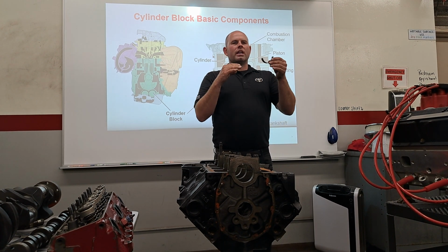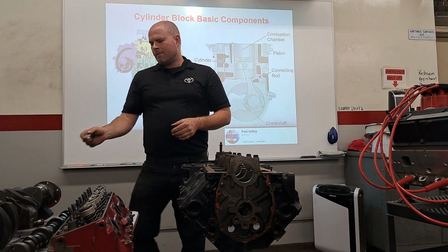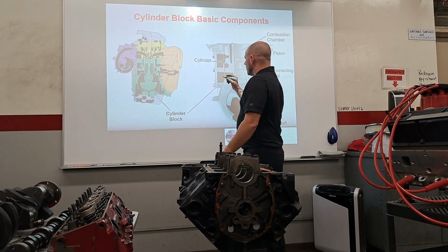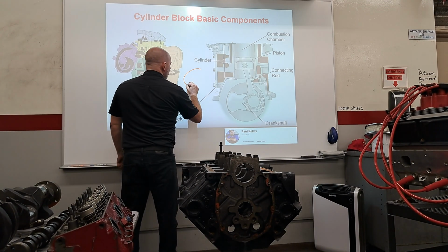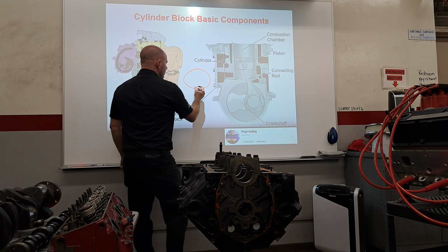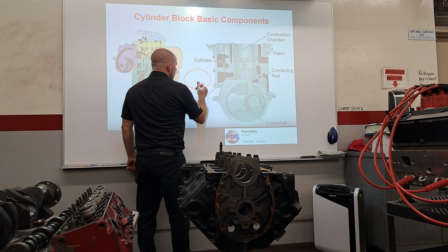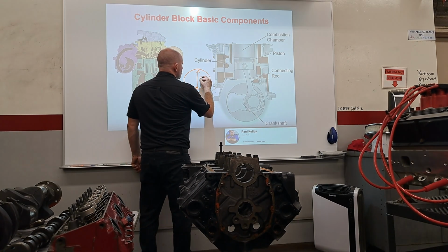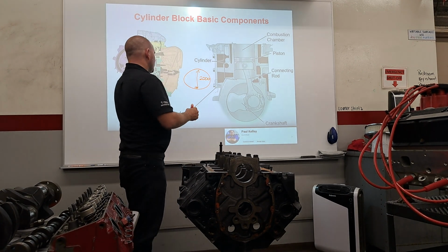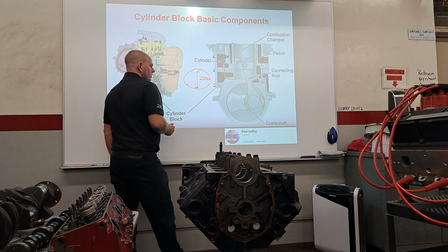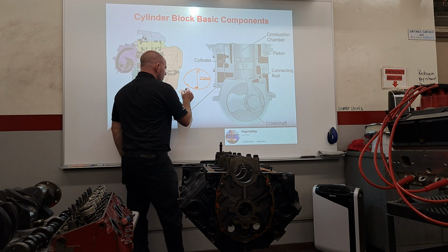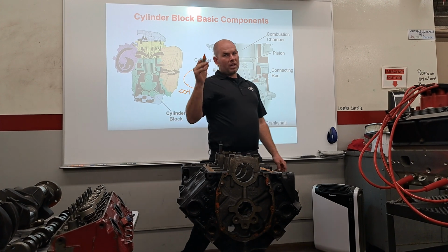Now, if you want to understand a little bit better, I'm going to give you a quick sample for math. Math is fun. Here we'll draw our crankshaft, and let's just make it really easy numbers. Let's just make this 2.000. Cool? Exactly 2 inches. Now, if we were to cut this down, and let's just say, because it was spun or whatever, we took 4 thousandths out of it, and then it was clean. And by the way, there's other measurements we need to do.